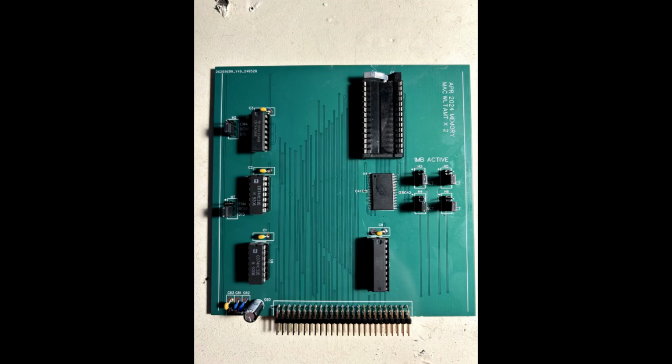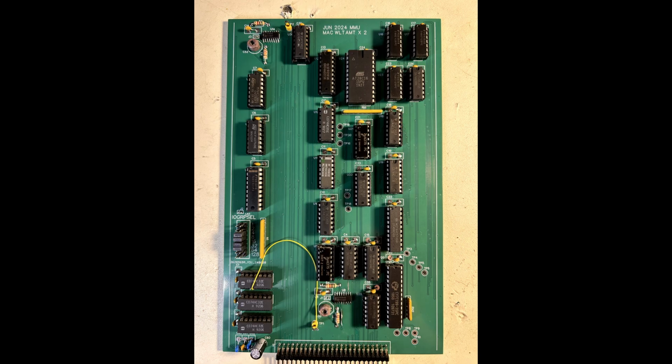I've increased the available system memory. The prior system had 256 kilobytes of RAM. This new system has 1 megabyte of RAM. I've also added a socket for an optional 64 kilobytes of read-only memory once I have a stable OS to use. With 16 banks of 64 kilobytes to address, I needed to add some additional address lines to my memory manager unit design. This unit now controls address lines A16 to A19.